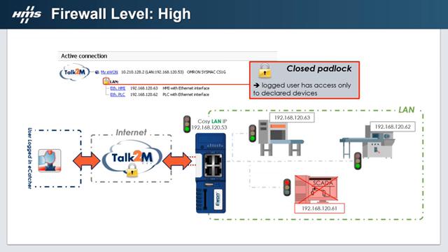So in this case, the connected user can communicate with the PLC on 62 and the machine on 63, but the SCADA on 61 is not defined and therefore communication is not possible anymore over the VPN connection. These restrictions are not applied locally, but will only go over the VPN. When the connected user pings the 61 IP address in this case, there will be no response.